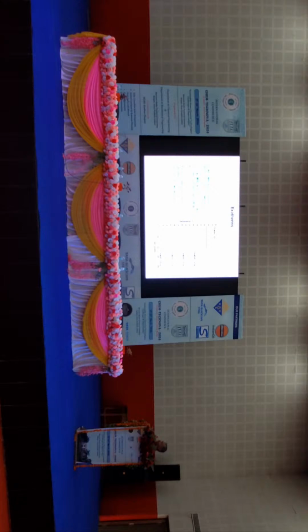Next one, please. Here you can understand the curing behavior. You can see the temperature rise during the exotherm, the heat evolution during curing of the resin. With higher MEKP, there are a lot more free radicals, because the catalyst always supplies free radicals. With those free radicals, more curing reaction happens, and the temperature shoots up in less time.